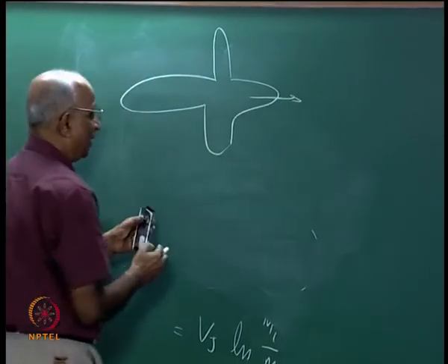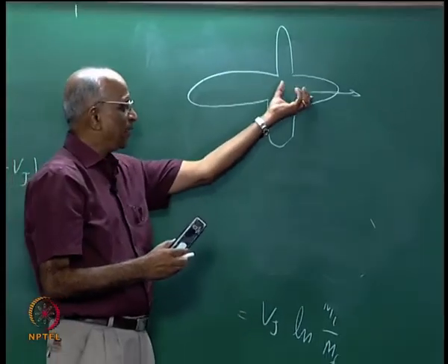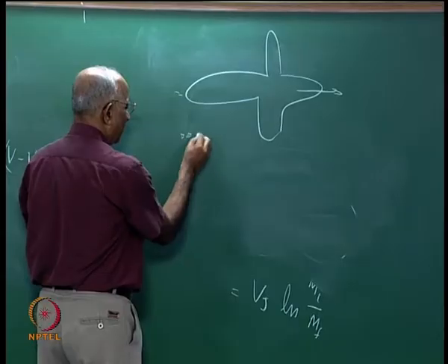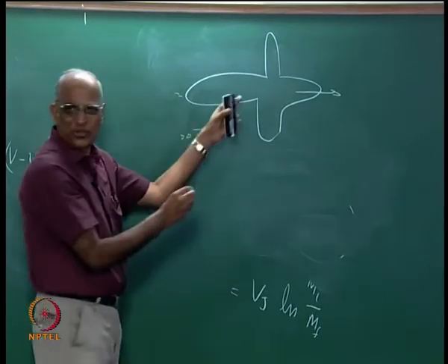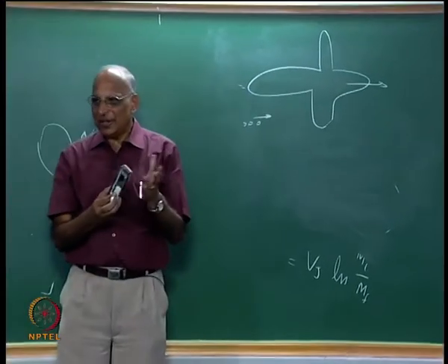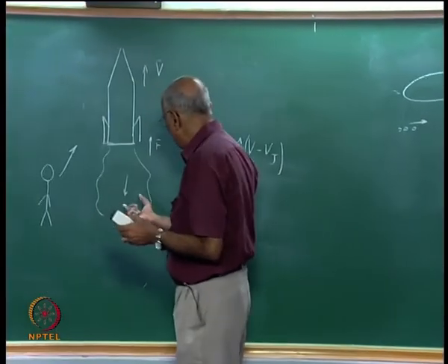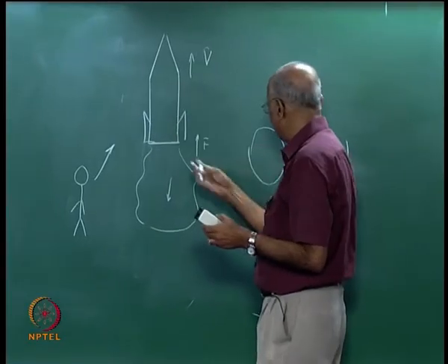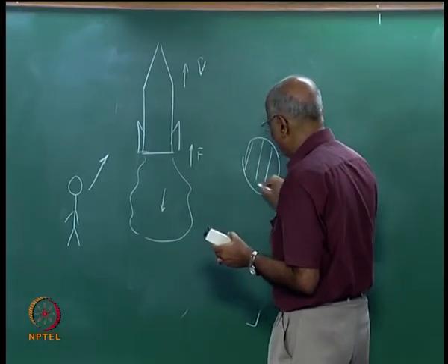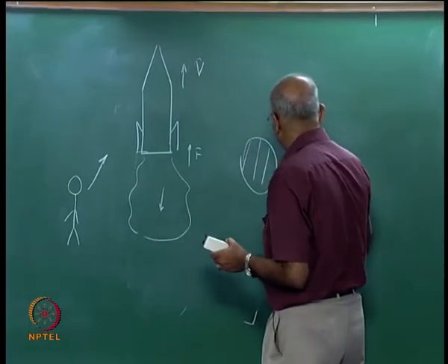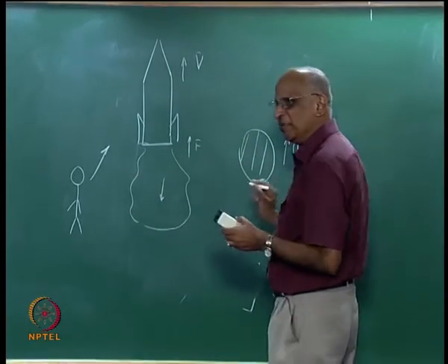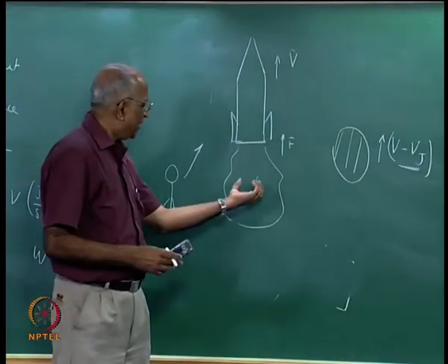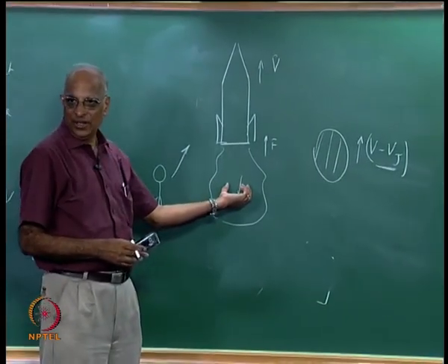The aircraft is moving, you see the aircraft going, and then you will find the smoke from this trail is also following this at a slower speed, right. Why does it have to happen? Maybe because this fellow is leaving the rocket with a velocity Vj, rocket is moving with a velocity v, therefore you see this particular jet or plume as it were following it up with a velocity v minus Vj. Therefore, what is being wasted? The energy content of this is getting wasted because it is getting lost.